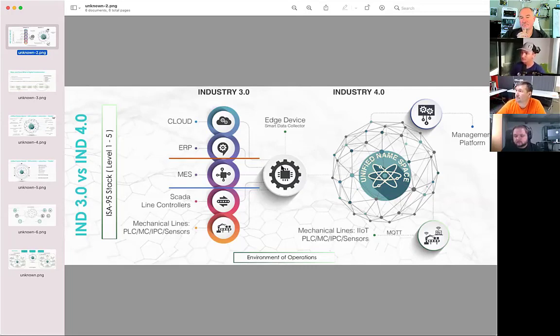And what you're going to want to do is, from everything to the left, it can be pull response, it could be Modbus, the traditional legacy stuff. But everything going forward is either going to be a smart device natively, or you're going to put in an edge device to publish it, converting it into your IIoT ecosystem, right? It doesn't have to be MQTT. We like MQTT because it's one of the best right now, but it's got to just be edge driven, report by exception, lightweight, and open architecture. And then you can create this ecosystem. And that's where the magic happens, right?